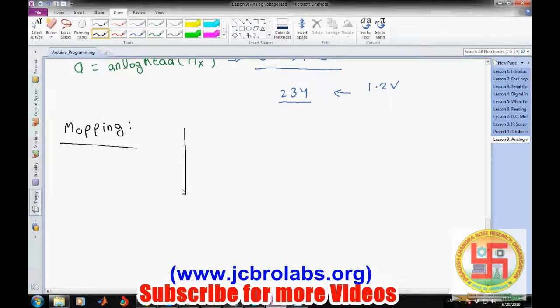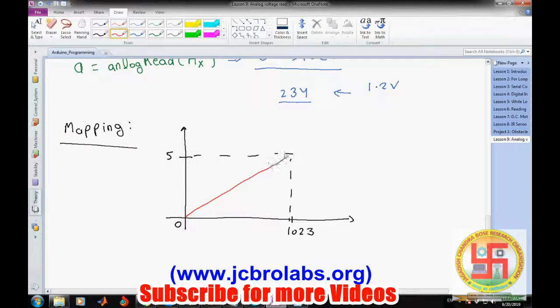So it is very easy, right? Here we have the input voltage 0 and maximum 1023, and the output we want, because we were using V reference as 5 volt, is 5. Because it is a linear relationship, we just need to identify the equation of this line. This is V out and this is the input.